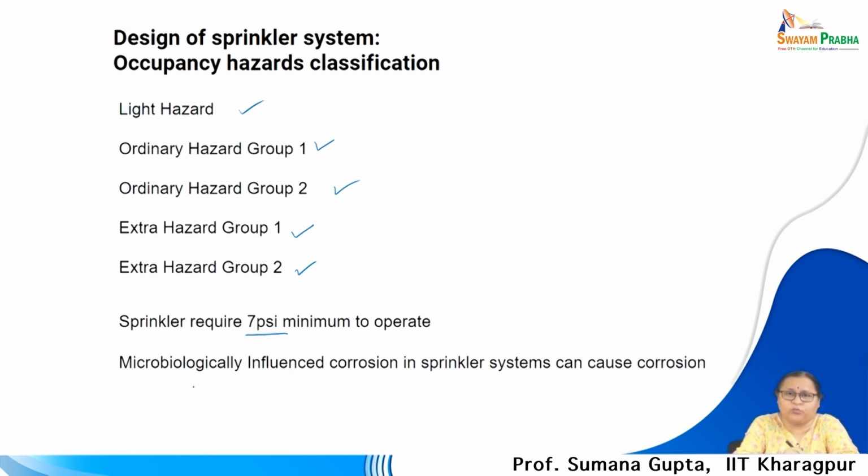and also the water quality, as I have told you, should not be affected microbiologically, because it should not be static water, and that can lead to microbiological growth, and that can influence corrosion, because with running length the pressure also falls, and the corrosion which can always happen within the pipelines, which are mostly cast iron pipes for water supply, can help in reducing the water pressure.